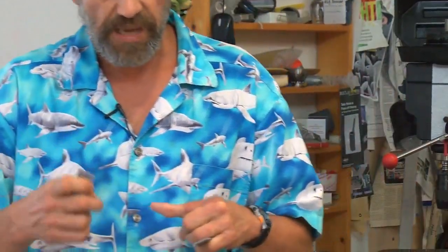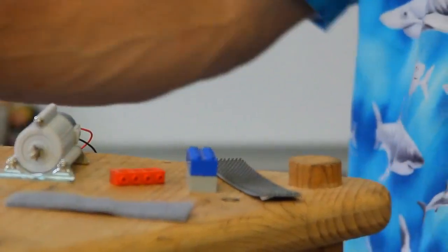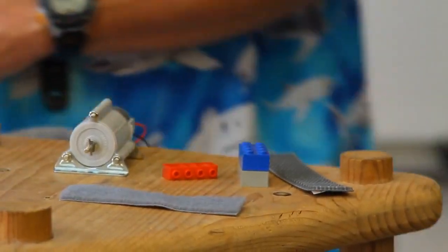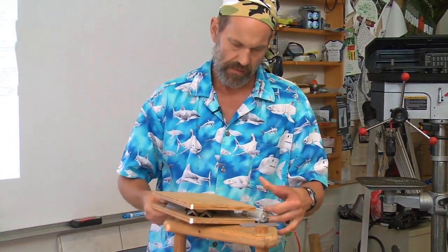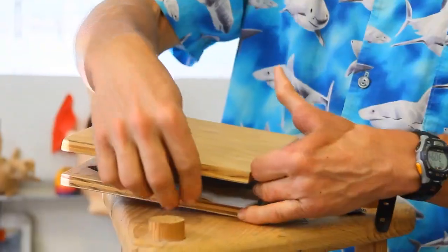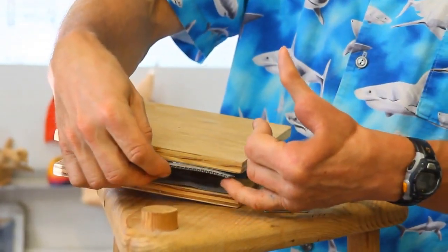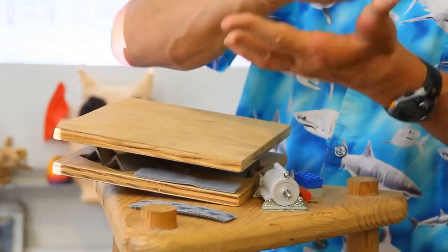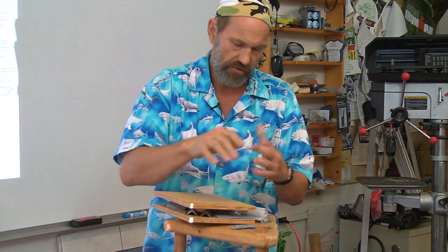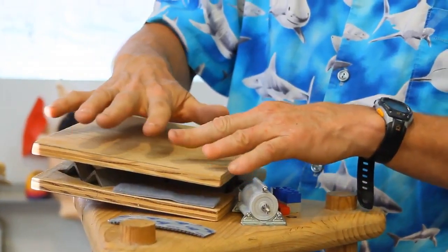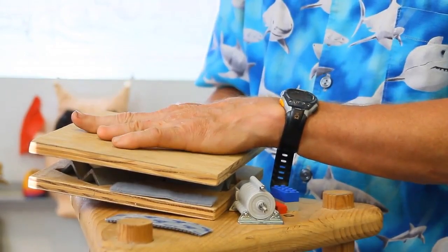Does that tell me, for example, that I could take something that looks like a kinematic coupling and put Velcro in here to help hold it together? And the kinematic coupling's job is to first align things, and then when you preload it a little bit, the Velcro engages, or you won't get enough collapse in it. I think this might be too stiff for a three-dimensional kinematic coupling.